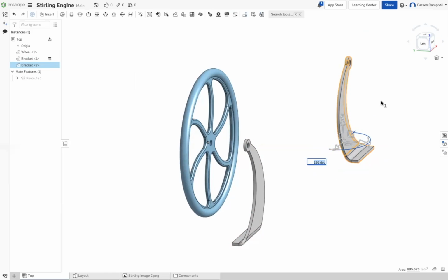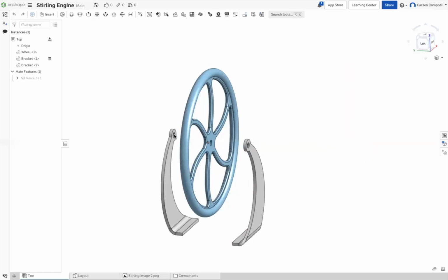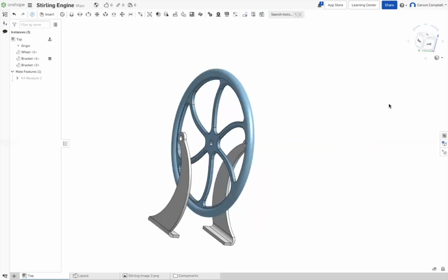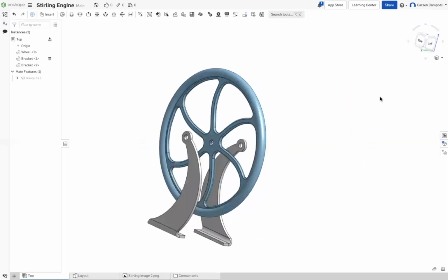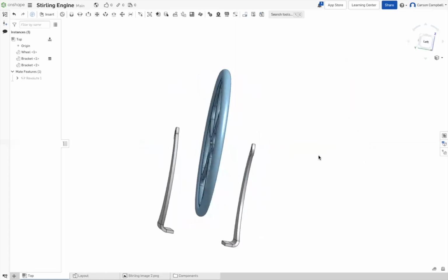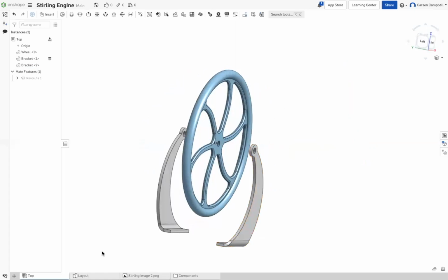Accept that. Click the white space, hit enter, and drag that bracket over to where you think it belongs. I mean, it's going the wrong direction, right? Yeah, I know. It's a mirrored part. That's why. Oh, sorry. So that's where I was trying to get. How do you create a mirrored part in the assembly? You can't. Can you still use this geometry and then flip it and create another part? Let me show you how to do it.